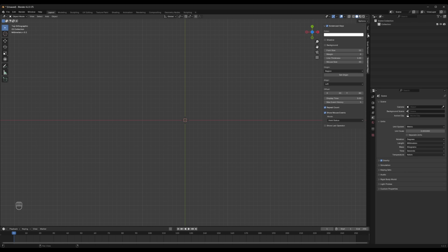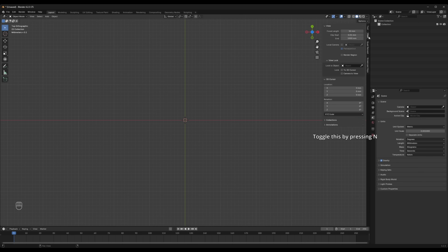And then after that, we just need to make sure that we change a few things so that as we're zooming in and out, our new settings don't begin to clip. So in the clipping, what we want to do is set our start clip to 1, and then for our end clip, we'll just add 2 zeros here. And this will make sure that as we're zooming in and out, nothing we add will just clip out and disappear.